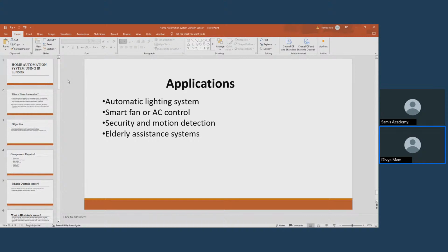And then we understood without adding the relay module and with adding the relay module. So what is a relay module? Relay is an automatic, electronic switch. What it will do is when a signal is given, it will turn on the 12V device. With the 5V signal, it will turn on the 12V device. So it's like a motor driver. With a motor driver, the special thing is we can control the movement of the motors, whereas here, we can simply switch on and switch off the devices connected to the relay. So relay is an electronic switch.